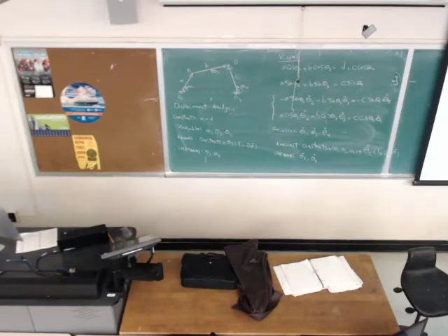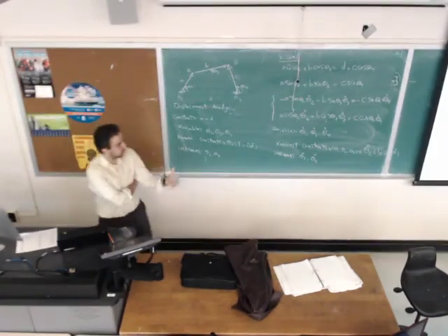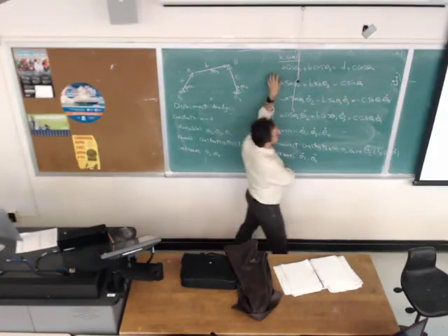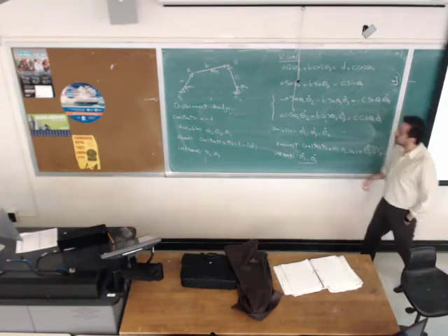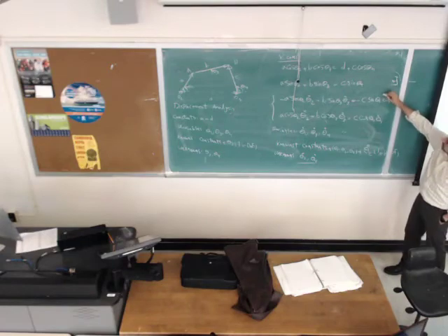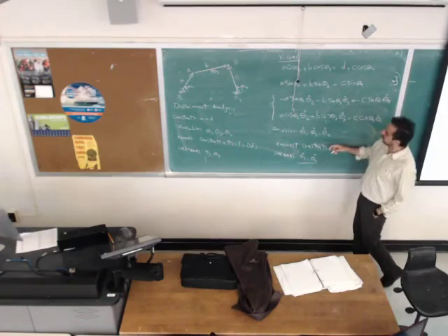Any questions on this? Everybody can see how we differentiate both sides, because I'm going to do this for the next mechanism. In the future, for any given mechanism, you are supposed to differentiate the displacement analysis to get the velocity equation. All right, two equations can solve for two unknowns, which are theta dot 3 and theta dot 4. The other terms, theta 4 and theta 3, are known, coming from displacement analysis.